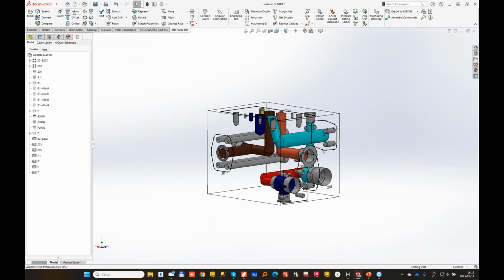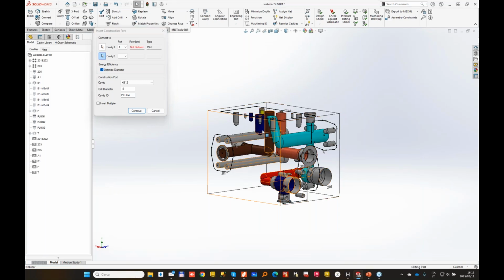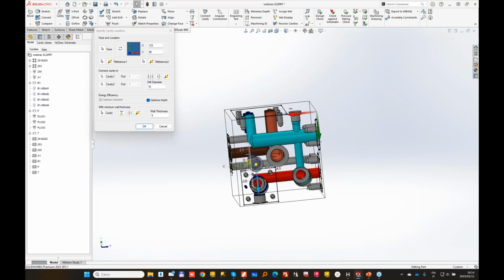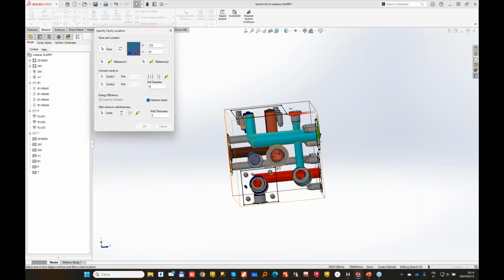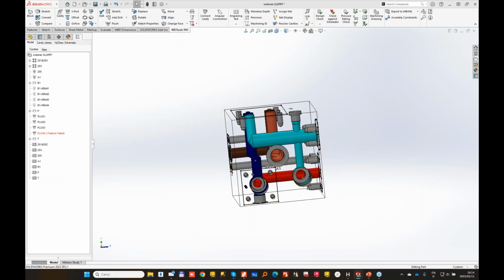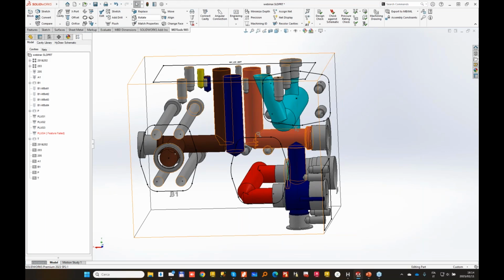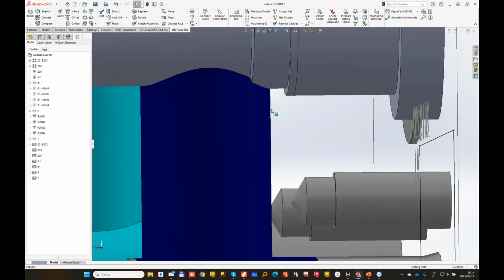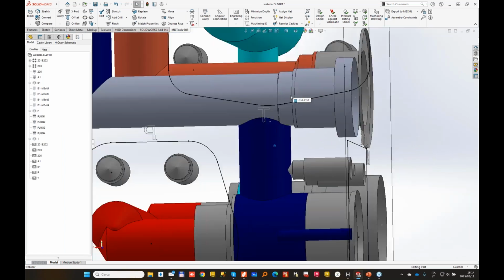And I want to use the same plug to do the connection. 1x2 and position here, and move it down. And this is going to make a connection. Maybe here I can have the same problem of zero thickness. In these cases, it's always some tangent position that should be solved just by moving this cavity by maybe some fraction of a millimeter. So when you have zero thickness, in that case, the problem was tangent with the